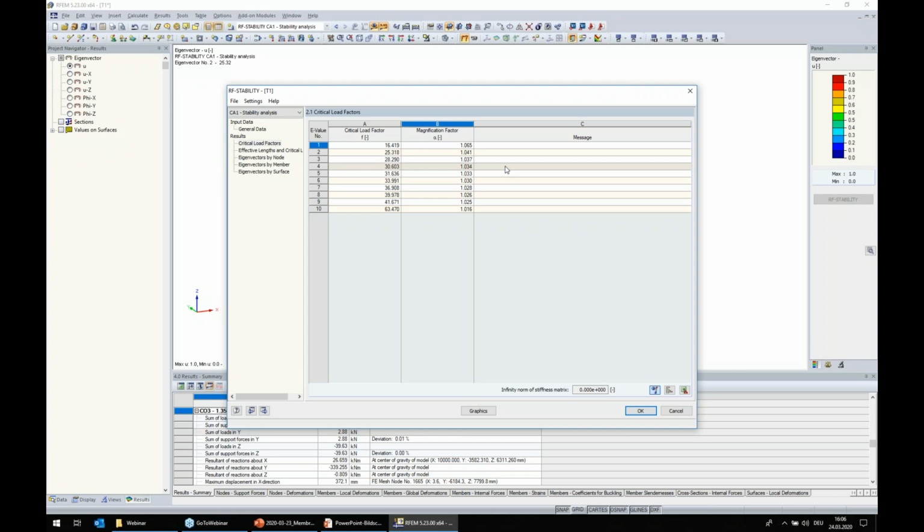We get geometrically nonlinear internal forces for design with a stability effect, with a P-delta effect, assuming some imperfections coming from wind loads. With this statement, we can say we can design the members according to cross-section proof plus stability checks, but with real buckling lengths, and this buckling length is member length, and this is quite easy.